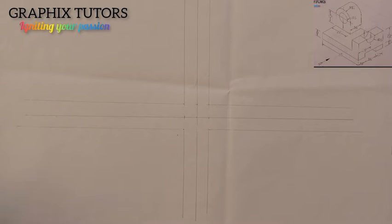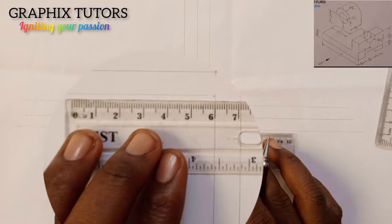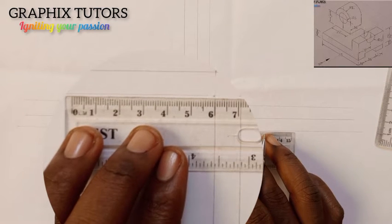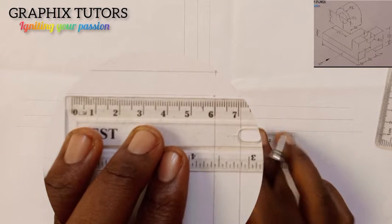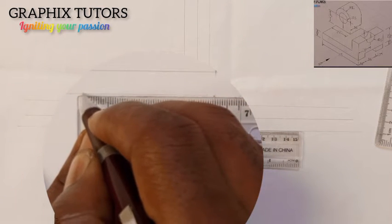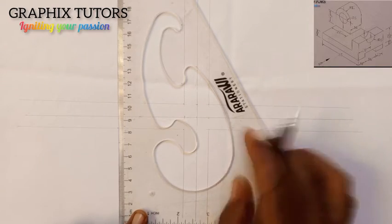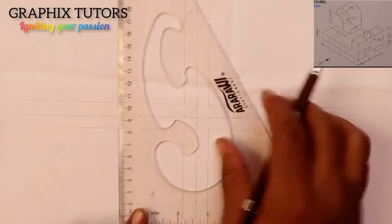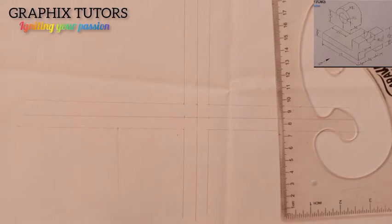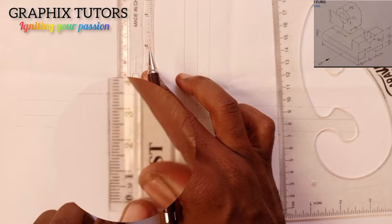So if I should place it here with my meter rule on the third quadrant here, because I want to draw in third angle projection, I will draw it here, right? So I said the total length is what? Is 55. So this is 55 from here to here. This 55, right? And I will draw it down this way with faint line. And I said the total height is what? 34. So I'm going to measure 34 from here. This is 34 here.